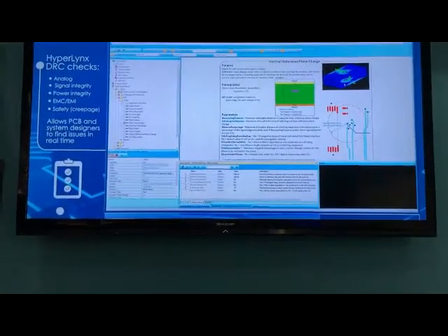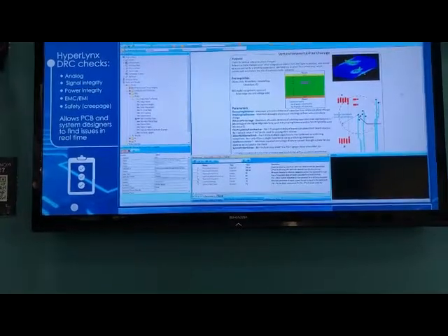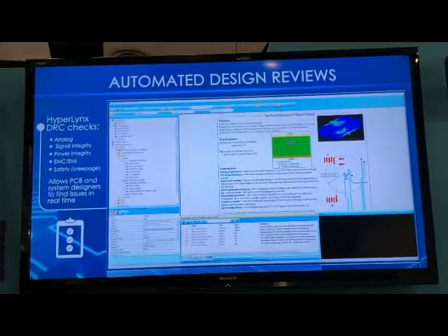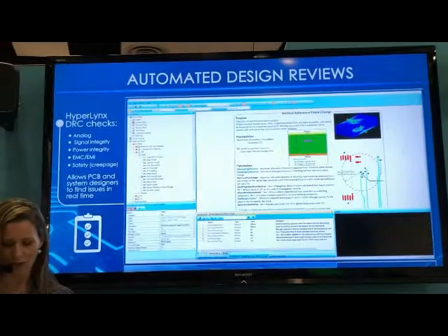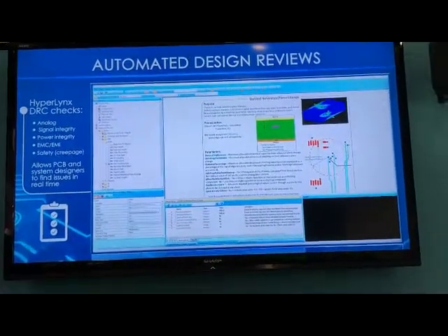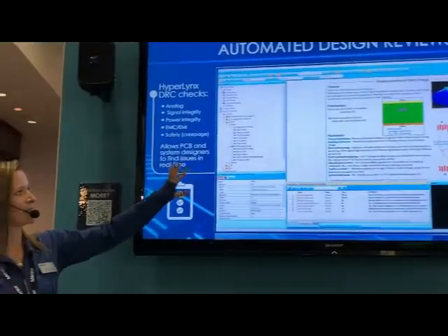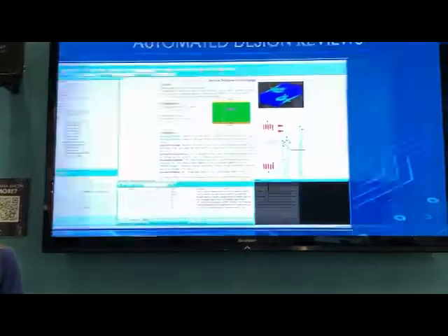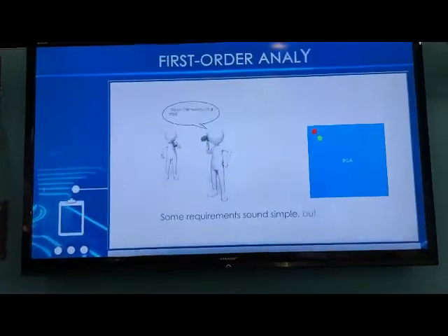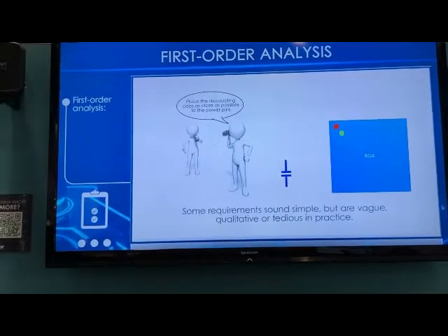Another example is this return path discontinuity through a vertical reference plane change. Now this is really hard to see because you're looking down at 2D CAD data and it's not apparent, obviously, where the return path will be running, right? In this 3D view, in a simple structure, it's easier to see, but in a 2D typical CAD view, it's not. Here's an example. This doesn't sound exciting if we're talking about simulation, right?